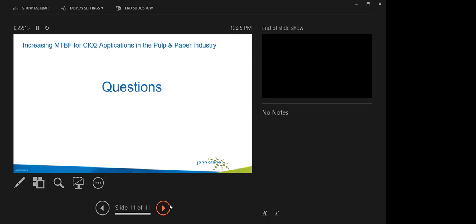Does the addition of the excluder change operating parameters? No, it's still the 250 degrees, and that really goes back to the barrier fluid itself being considered water. Unless you're operating at much higher temperatures that we're evaluating, then we might remove the excluder, because it's only good to about 300 degrees F, because it is a PTFE material.